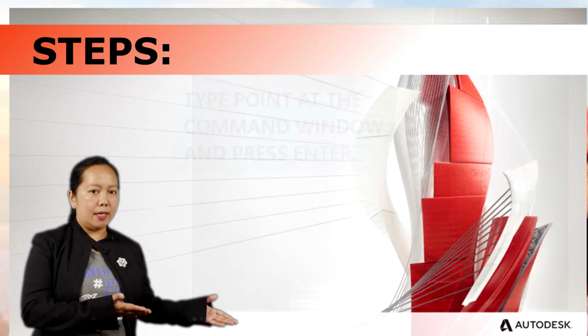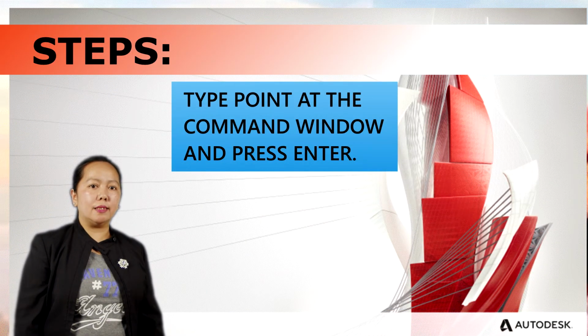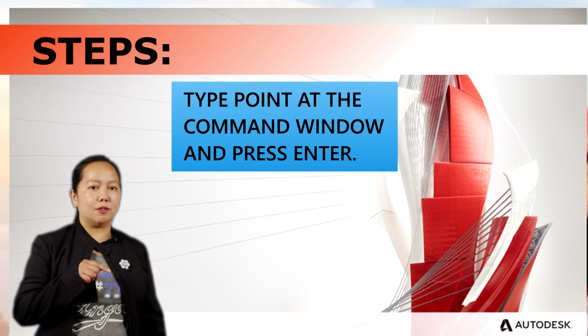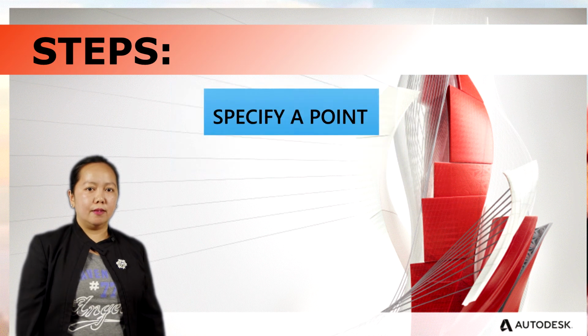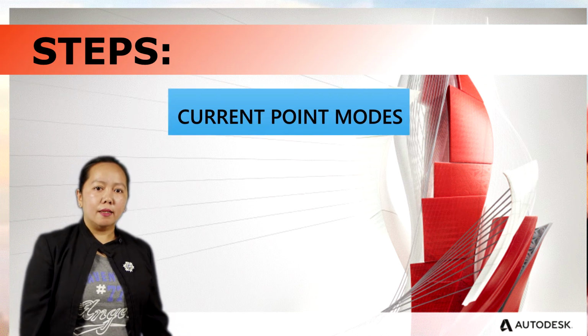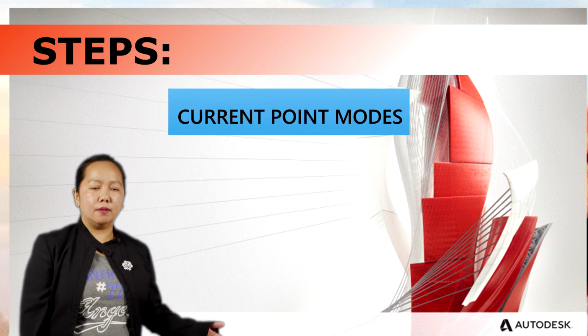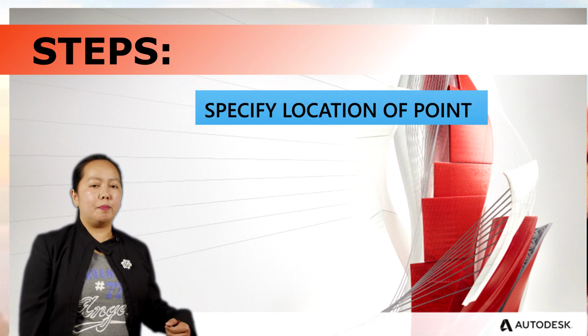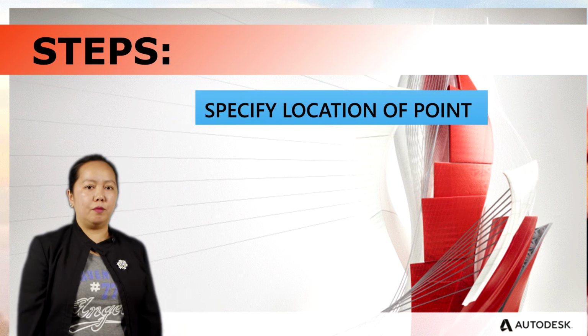Steps. Type point at the command window and press enter. Specify a point. Current point modes. Specify location of point.